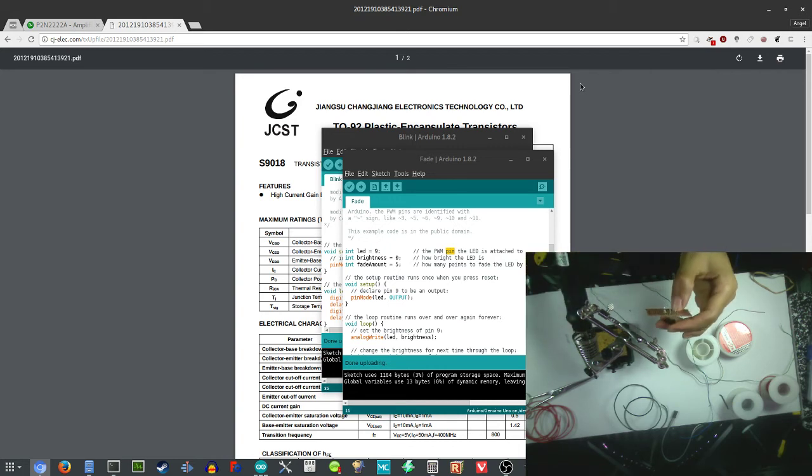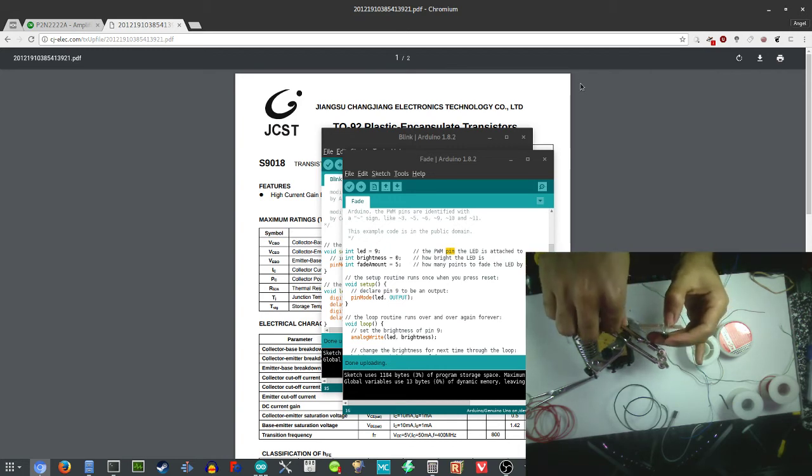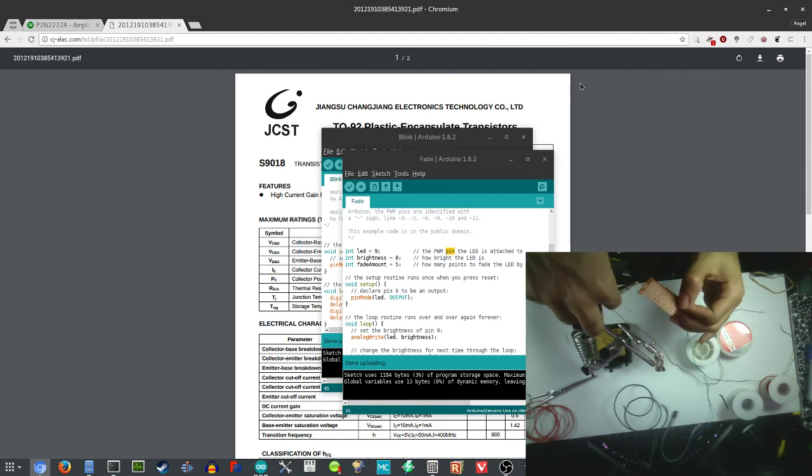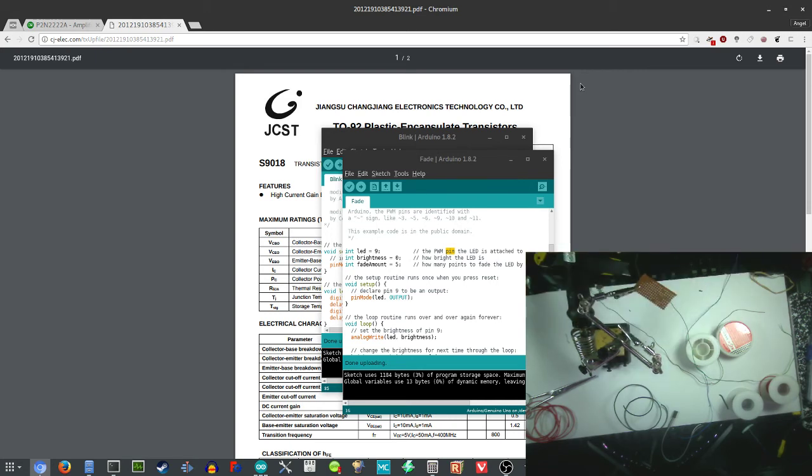Iron is hot. So how I'm gonna be soldering them is tacking them in place with a little bit of solder, and then I'm gonna push it up and heat it up, and then leave it where it's at.